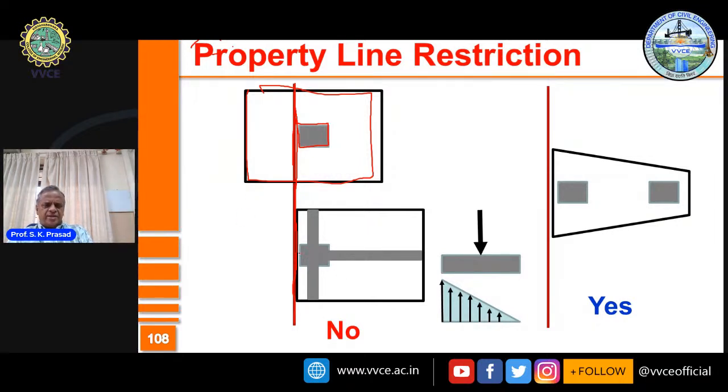Many structural engineers decide on something like this. You have the column here, and they say, you put the foundation. I mean, you put a rigid beam here. You also can put a rigid beam here. It's not going to help because when you take a situation like this, the entire load is eccentric, maximum on this side, and it may be close to zero or it may even be lifted up. Therefore, there may be separation. So these two are never acceptable.